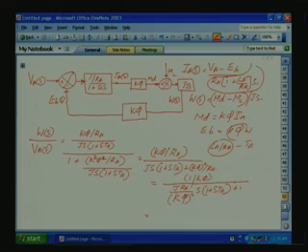what is the unit of this? This will have a time constant of seconds. This is another time constant, and it is called the electromechanical time constant. So, the final transfer function will be 1 by K phi divided by S TM into 1 plus S TA plus 1.